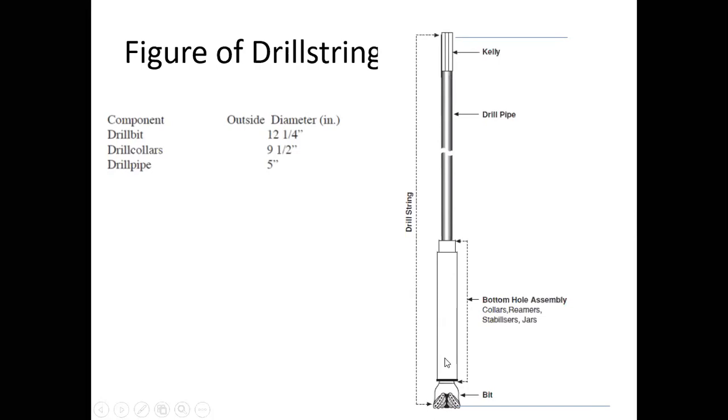So the lower portion provides the compression, the upper part of the drill string provides the tension, and then we have a neutral point where there is no compression, no tension, zero forces acting on this point. Remember, when we are talking about the drilling process, the whole hole is filled with fluids, drilling fluids.